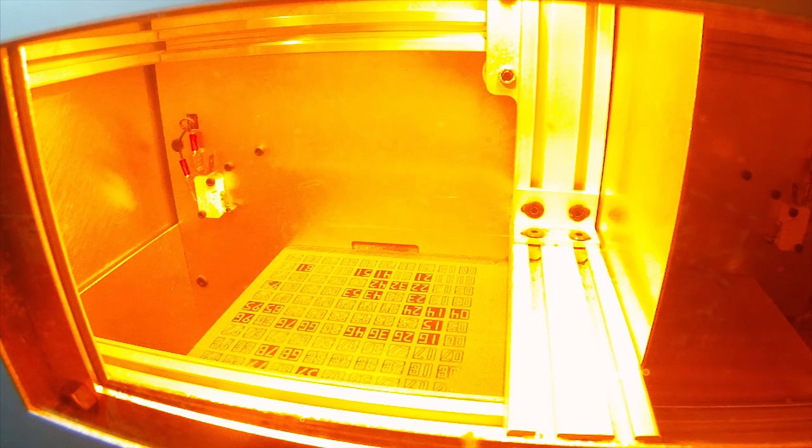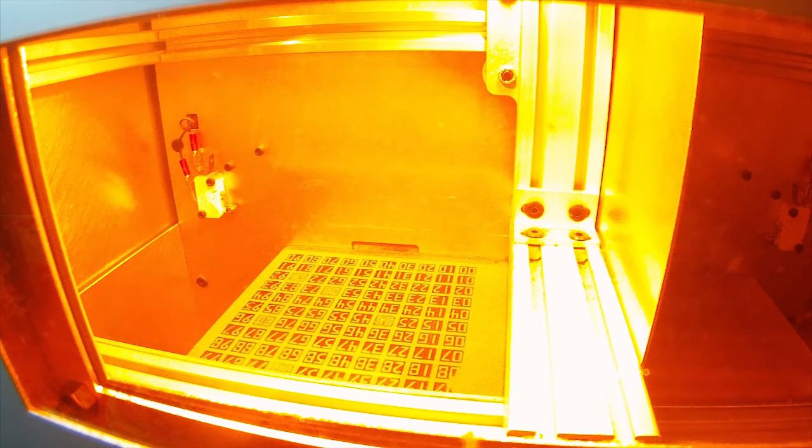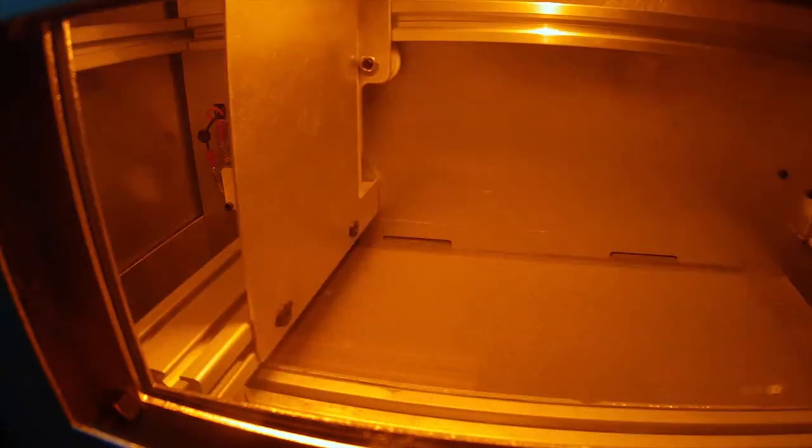My overall advice is just to avoid putting the corners in altogether. So 00, 09, 99, and 90. Those squares I'm going to remove from my calibration grid just because no one should really even try to get those ones to sinter. And running the calibration grid is just going to be this cycle of trying to get a few squares to print without it plowing them all the way through the other side.